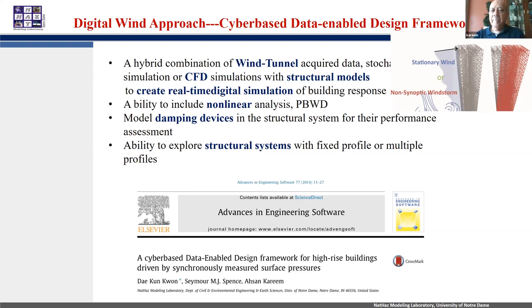As some of you already know, there is interest developing in performance-based design for wind to consider buildings going inelastic. That's where the nonlinear analysis part will come. Many times in these buildings, we have to put in damping systems, which could be a tuned mass damper or distributed dampers. Once we put that into the structural system, typical frequency domain-based methods may not be that convenient. So the time domain approach works very well.